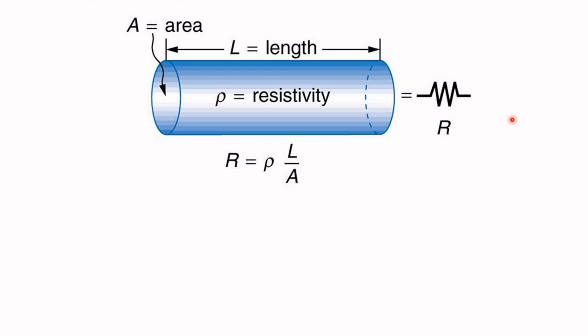So if you take a unit volume like a unit cube, when the voltage is applied across these spaces, the resistivity is expressed in ohm meters, because the length and the distance are involved. So we take it as ohm meters, ohm feet or ohm centimeters also. This parameter is independent of the size and shape of the object or substance. The resistance offered by a substance is a function of the resistivity, size, shape, and points of measurement. So wherever you take the measurement, you will have a different resistance value.